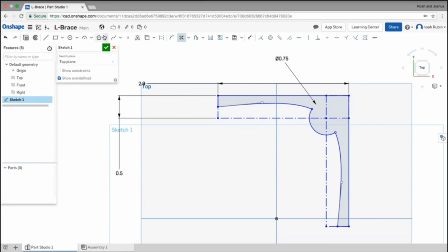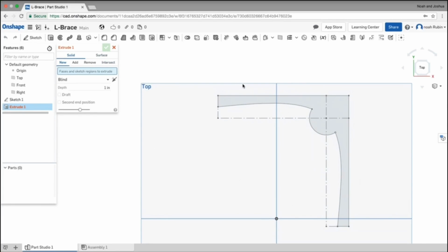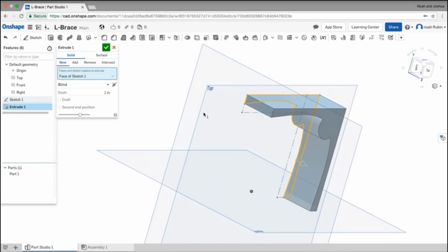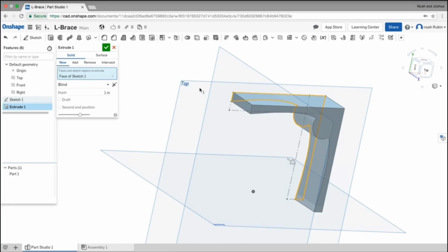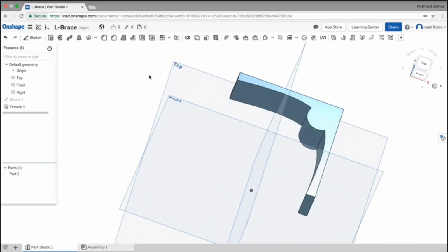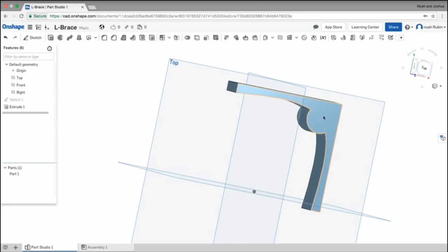We can then add in a little bit more geometry if we wanted to, but I think it looks pretty good right now. You of course could add text here, but I'm not going to do that right now, so we will just press check here. And now extrude this, and let's extrude it a good inch, I would say. Yep, I might change that between now and the time I print it, but we'll extrude it an inch, and you can see that there's a little bit of extra, like this area here might be considered wasted filament.